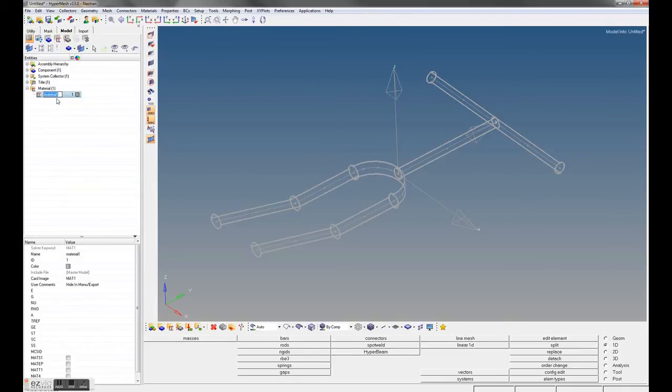We get this little thing showing up here, and then also the input fields down below. So I'm going to call this steel because it's steel, and go down here to input the properties. This would be Young's modulus, which would be 30 e to the 6th, and then we'll also put in Poisson's ratio, 0.29. And now this card is assigned those properties.